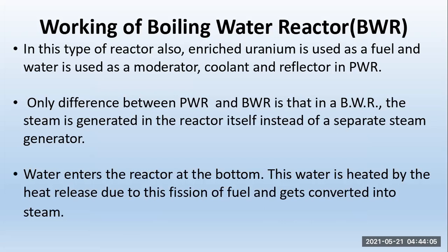The pressurizing tank included in the circuit maintains constant pressure in the circuit throughout the load range. The electric heating coil in the pressurizer boils the water to form steam, which is collected in the dome, as shown in the figure, and pressurizes the entire coolant circuit before starting the reactor. How to reduce the pressure? Water spray is used to condense the steam.